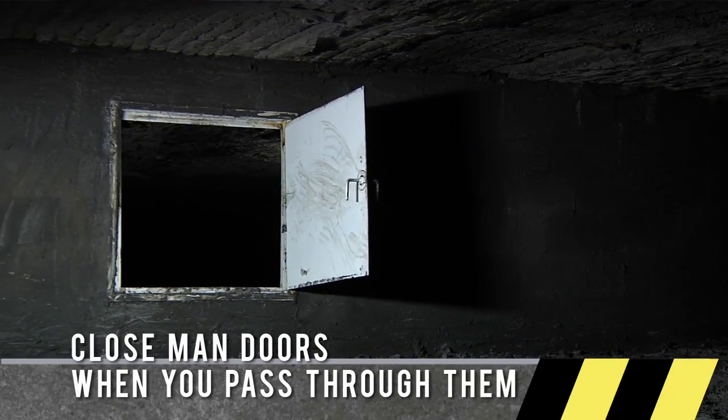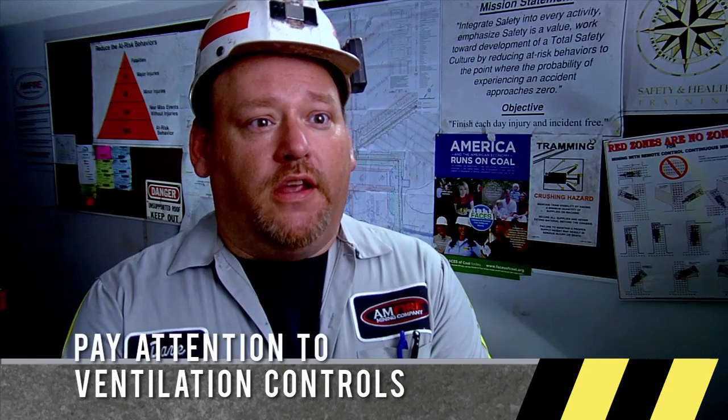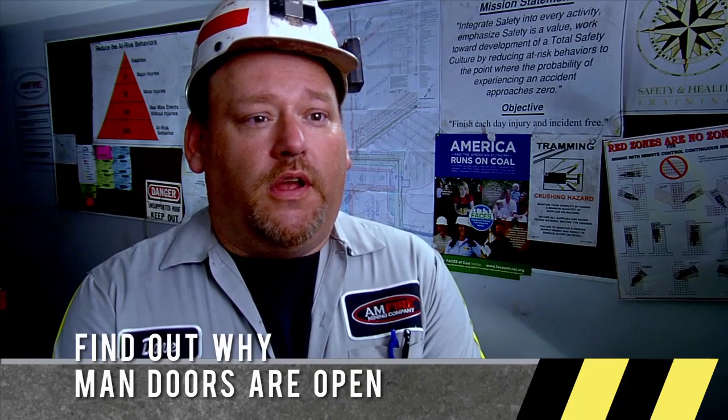If the ventilation control is not working properly in the mine, it won't direct enough volume of air up to the face. A miner working inside the mine, to keep the vent controls working at 100%, the biggest thing he can do is keep his eyes open. Look around, notice things, and see things. If you see a door open, it may be open for a reason, but ask if you're not sure. But if you go through a door or a check curtain or anything like that, if you have to move it, open it, you shut it. If you tear it down, put it back up.